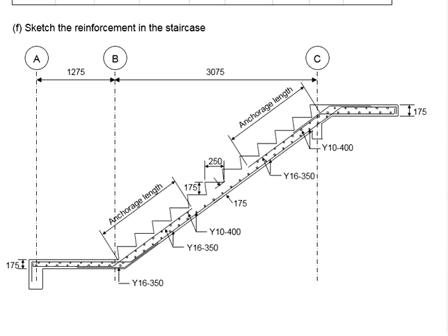To make it simple, if you use the required anchorage length of at least 50 times the bar diameter, it shall be longitudinal to the arrangement of the reinforcement. Now if you choose to define by the percentage of the anchorage length, either 20% or 1/3, this will have to be in the directions of the anchorage length, and then you identify where it should stop.